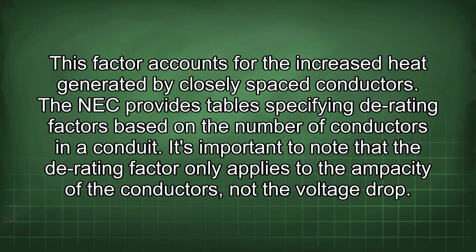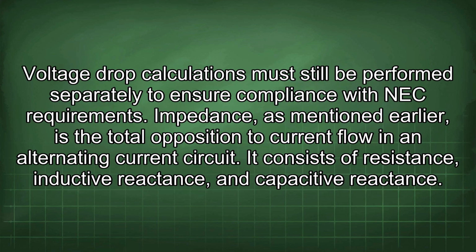It's important to note that the derating factor only applies to the ampacity of the conductors, not the voltage drop. Voltage drop calculations must still be performed separately to ensure compliance with NEC requirements.